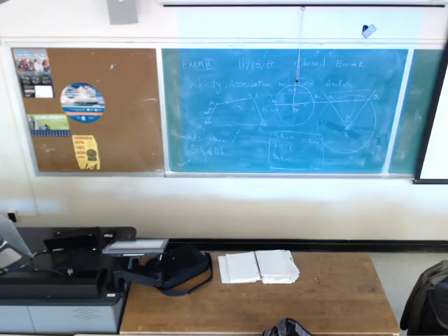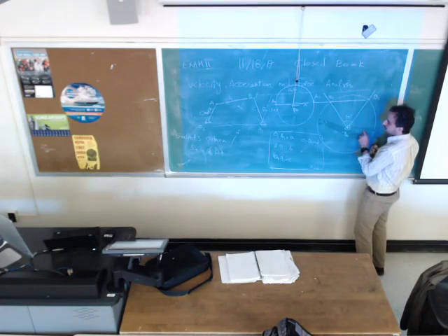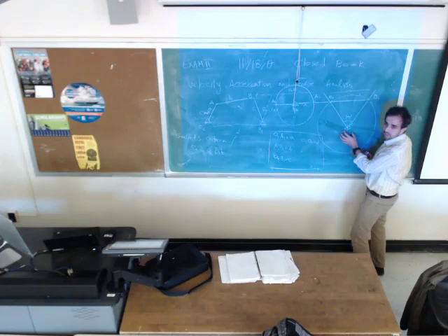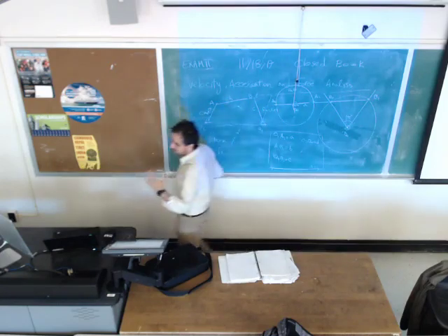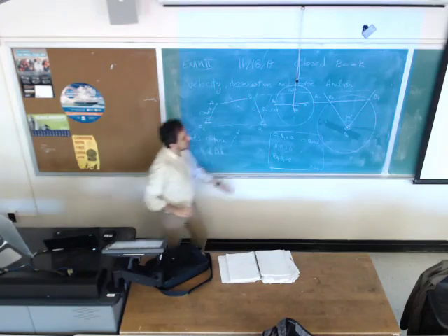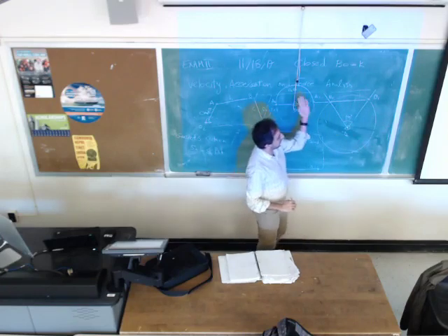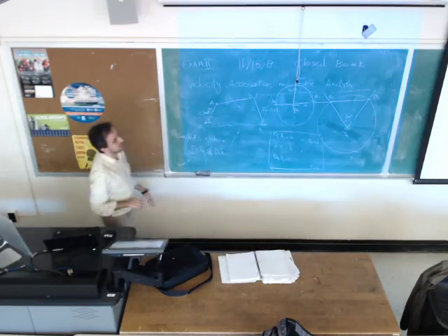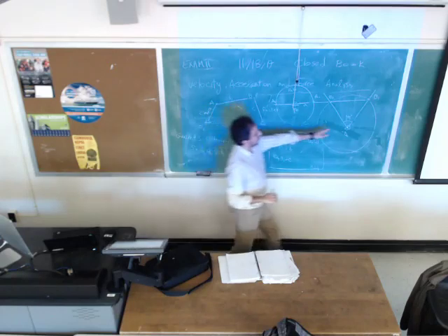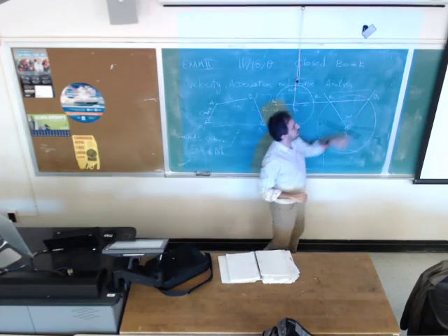Is that clear? For the first 2 choices that you said, the location of O4, the X position and Y position of O4, is not limited. You can pick any X and Y for that. Number 3 is the orientation of this line with the ground, 1 angle. Number 4 is on this line, where you are free to pick any point.